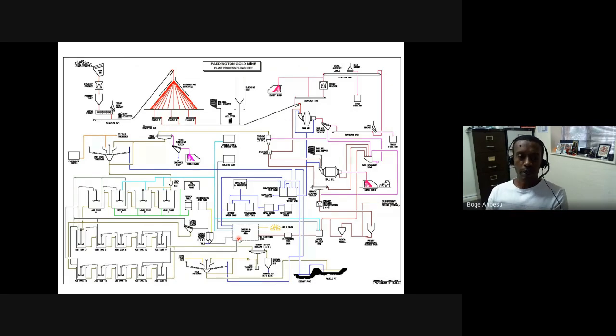So your crusher may require a separate metallurgical accounting for water, for material, for the valuable. Your grinding mills may require that. You may even have a thickener where you are interested mainly in keeping an eye on the water balance, how much water is being recovered from my thickener, okay? You can do that for leaching, where I have put this much gold into my leaching tank, how much of it is dissolved, how much of it is not. And you can do metallurgical accounting for a large portion of the circuit or the flow sheet that you have.